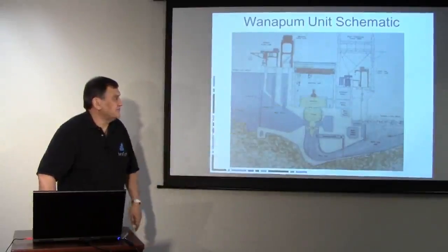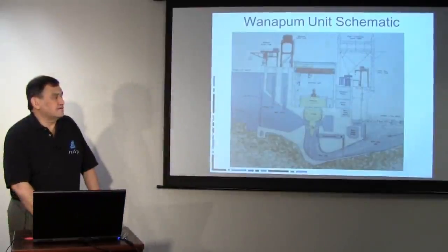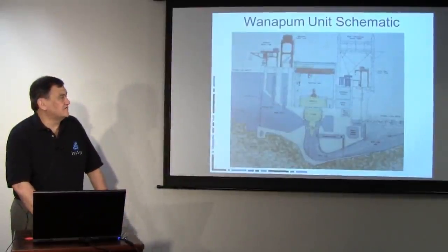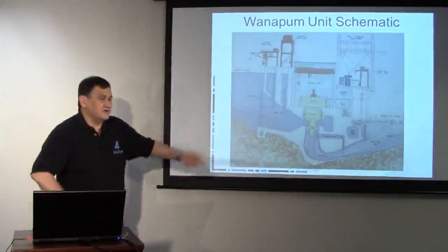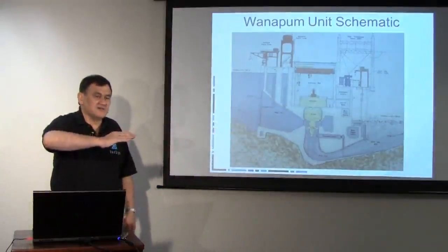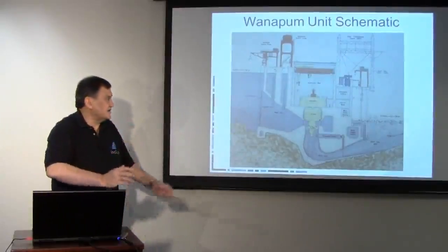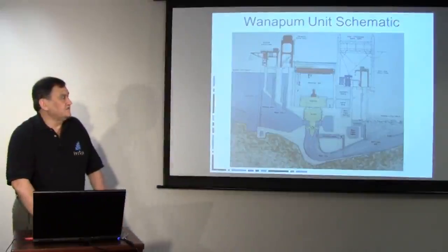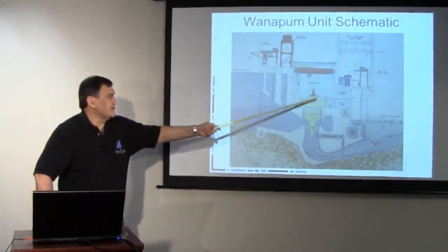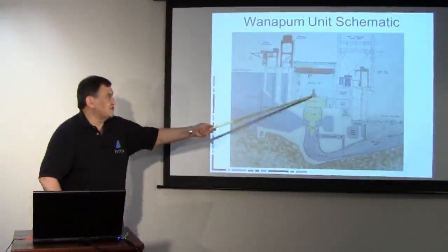So you need to have either local power from a diesel or from batteries to get that high pressure oil going into the thrust bearing, which lifts the thrust bearing just a fraction, and then you can start opening the wicket gates to get the turbine running. If you did not have the oil pressure running here, then you would heavily score and damage that thrust bearing.